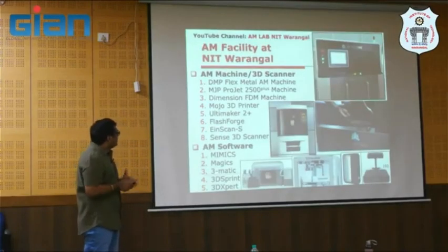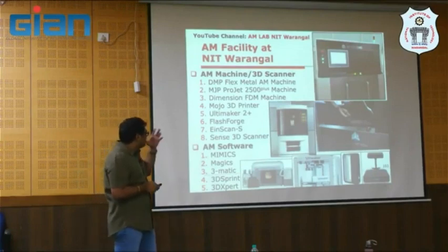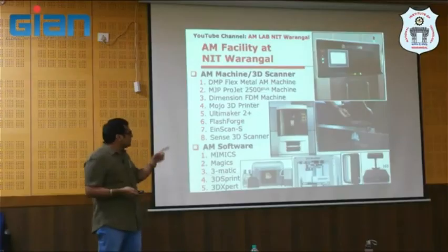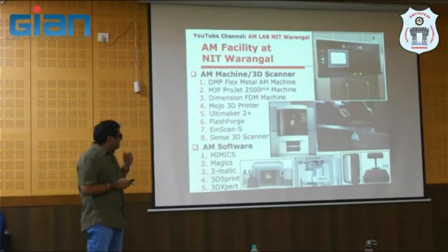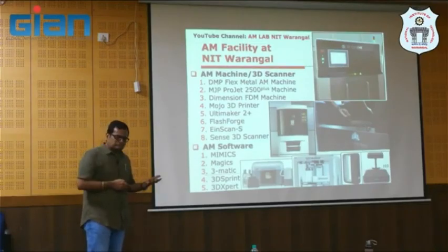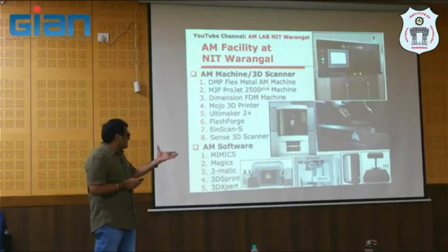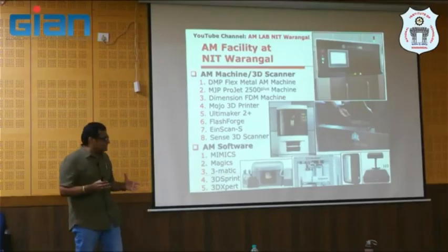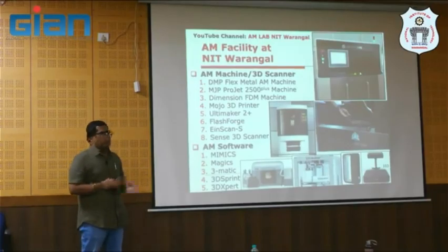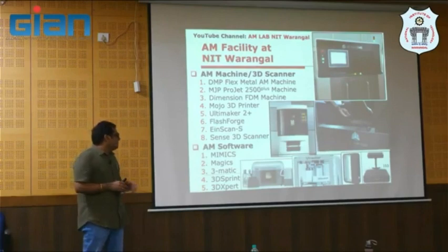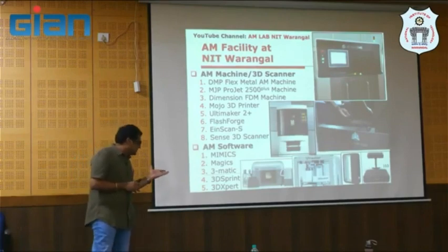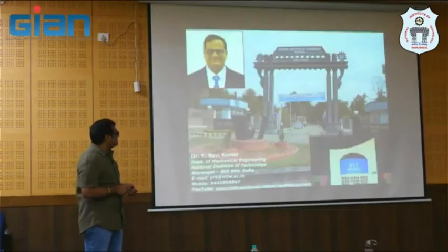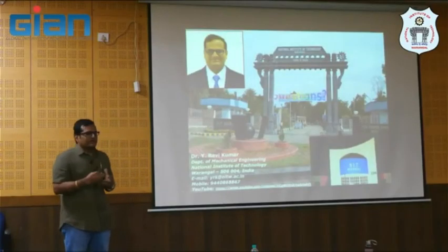Anyway, you are coming to the lab. These are some of the facilities we have. We have a DMP Flex metal AM machine, which we are going to show day after tomorrow. We also have a material jetting system, the ProJet 2500 Plus, two FDM-based machines, desktop polymer machines, and two scanners. And the software, exclusively for medical device design: Mimics, Magics, Materialise, 3D Sprint, 3D Expert. These are the AM software we have. That's all from my side. If you have any questions.